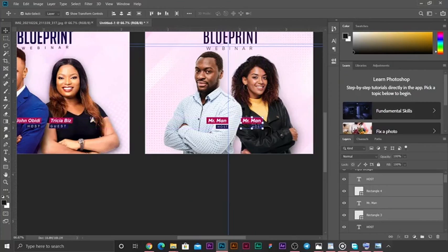But assuming the first part I took when I was going out was up, and then you hold the shift key, you see it has now locked it in the upward direction. I can't move left or right, it only has to go up. So we use the shift key to maintain the direction sometimes when we are making copies like this.